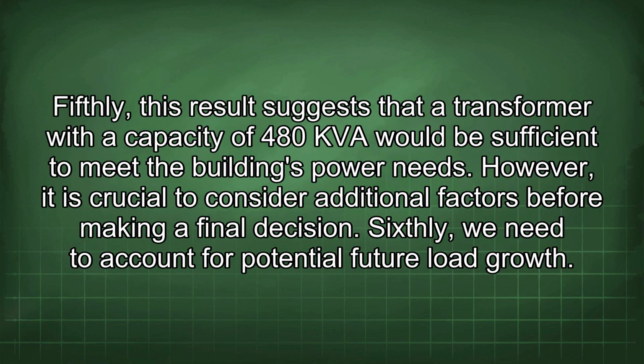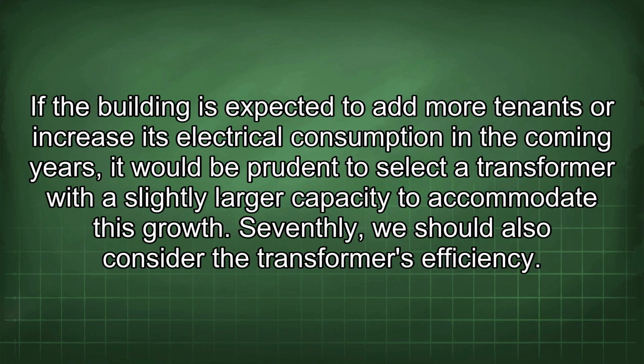Fifthly, this result suggests that a transformer with a capacity of 480 kVA would be sufficient to meet the building's power needs. However, it is crucial to consider additional factors before making a final decision. Sixthly, we need to account for potential future load growth. If the building is expected to add more tenants or increase its electrical consumption in the coming years, it would be prudent to select a transformer with a slightly larger capacity to accommodate this growth.